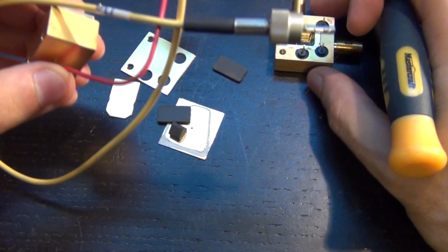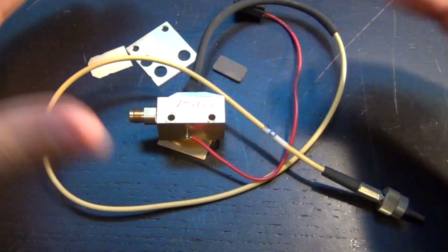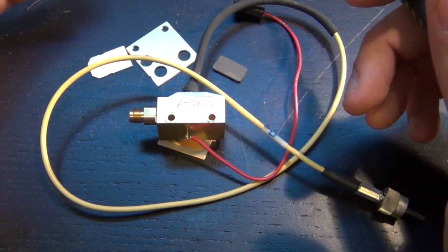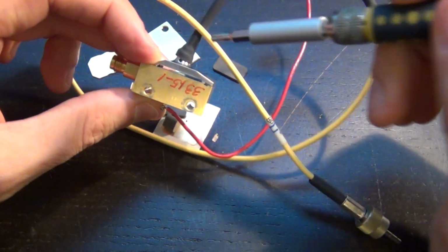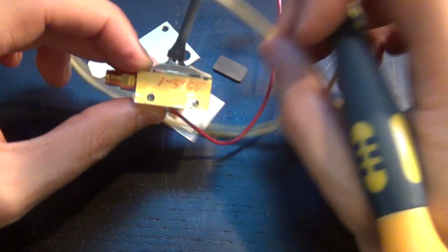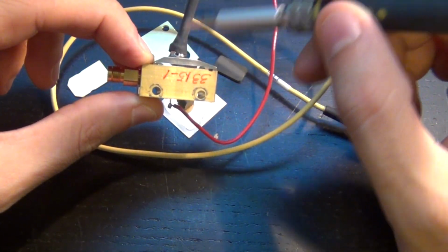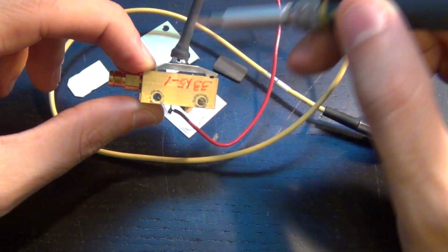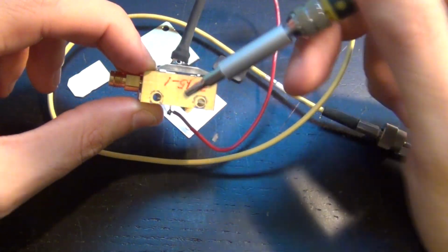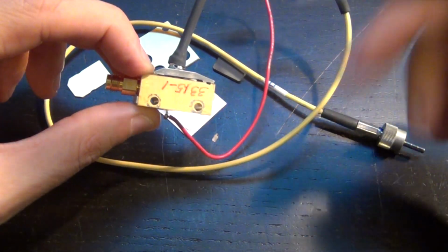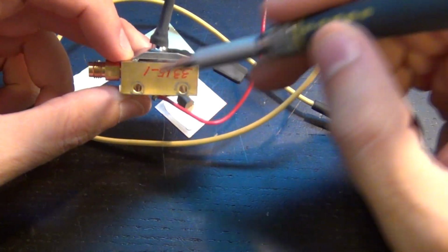And here's the optical one. I'm touching all these by hand because it's dead. You should never do this. You touch any of these things by hand without ESD protection, and you can be sure that they are dead. So this thing is interesting. Actually, this optical module is pretty old-fashioned. I mean, people don't build these this way anymore. You can see that the coupling between the fiber and the module itself is done through a collimator, and there's a gap here, so it actually shines through an opening on the surface of this into the module. They don't couple optics this way anymore, but this is an interesting way that I've seen this module built.